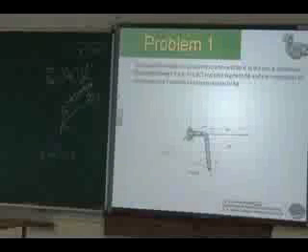Okay, so for force F only the magnitude is given. The force acting along BC, only its magnitude is given. But we have to find the force along AB, perpendicular and parallel to AB. So first we have to convert this force to Cartesian form. To convert it, we need to find the position vector along BC, RBC, and then RAB. Find the unit vector of RBC and multiply it, then we get the force along BC. Then force AB. So first step is the position vector along BC.